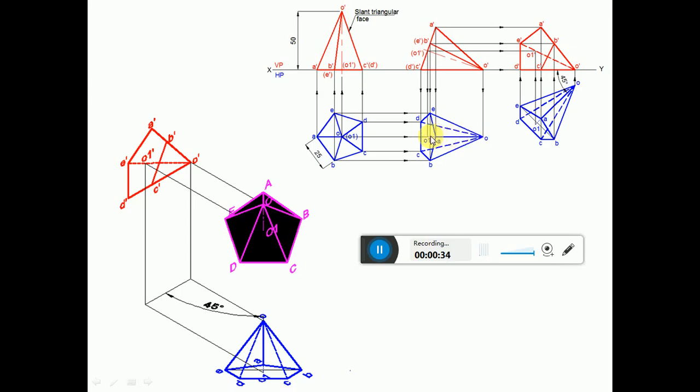Now, since the axis appears to be inclined, naturally he has given in the problem "appears to be inclined". So it is the apparent length, apparent inclination that he has given. So we need to rewrite the same sketch on that 45-degree line, because the axis here is also in apparent length, so the inclination given is also apparent inclination. From the projections of lines, always on the apparent inclination we are going to get the apparent length.